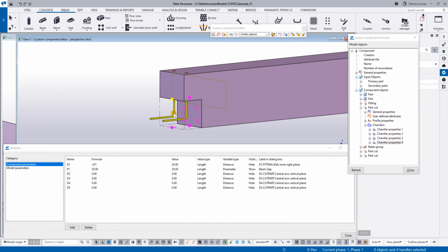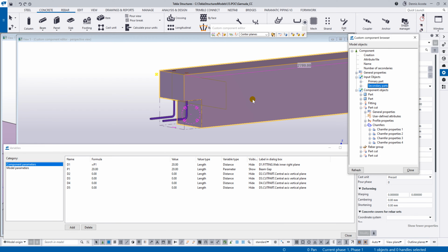Now, it is also very important for us because the beam here, there is no input in our component. We don't input the size of the beam in our component. The beam size is input during the modeling. So you model the beam, you key in the size of the beam, not in the component. Earlier, remember the wall, we key in the thickness and the height in the component. But this beam, no. This beam is something like you key in the size during the modeling.